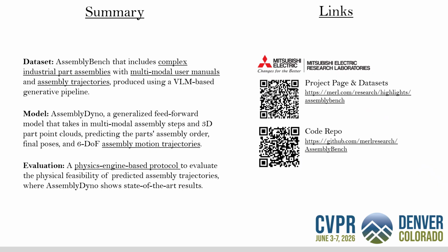In summary, our contributions are threefold. First, we built a dataset that includes complex industrial part assemblies with multimodal user manuals and assembly trajectories. Then, we proposed a generalized feed-forward model that takes in multimodal assembly steps and 3D part point clouds, predicting the parts assembly order, final poses, and assembly motion trajectories. Finally, we designed a physics engine-based protocol to evaluate the physical feasibility of predicted assembly trajectories, where our model shows state-of-the-art results.